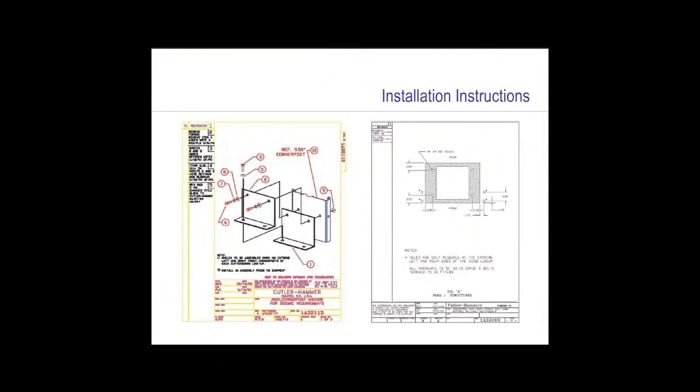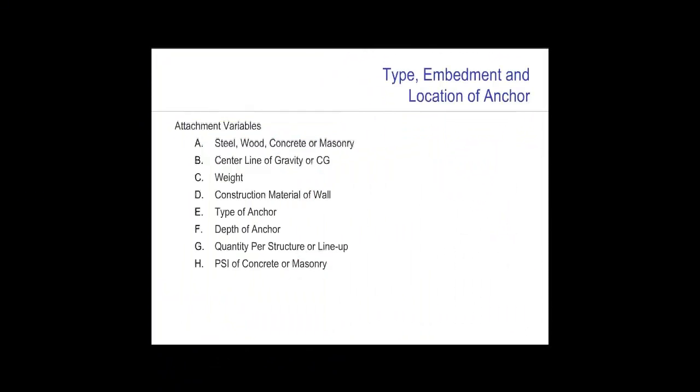Let's see why. Due to the almost unlimited variety of installation scenarios that may be encountered, the test of the equipment is based on specific mounting criteria for that test, and this provides a TRS, or test response spectrum. The TRS that is generated is then compared to the RRS, or required response spectrum, for the site-specific seismic criteria.